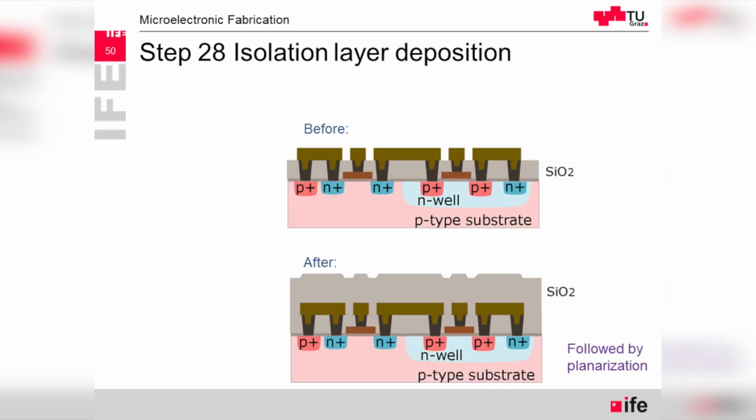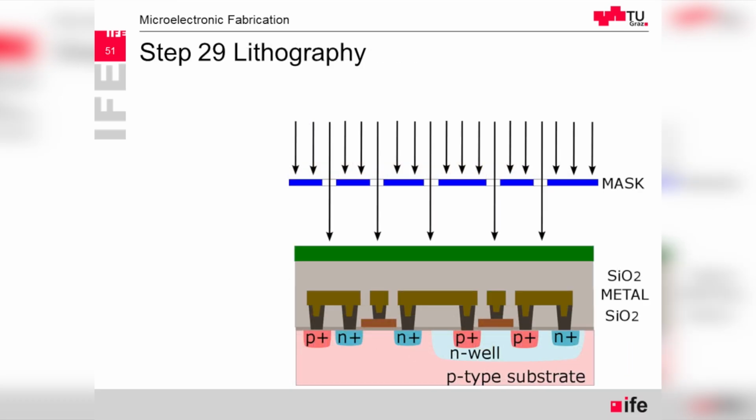Then we have, again, deposition. Here it's written silicon dioxide. On another slide, it was written silicon nitride. It's typically silicon nitride that is being used here as the insulation interlayers. Every step, we have planarization. And after the first metal layer, now it's quite repetitive.